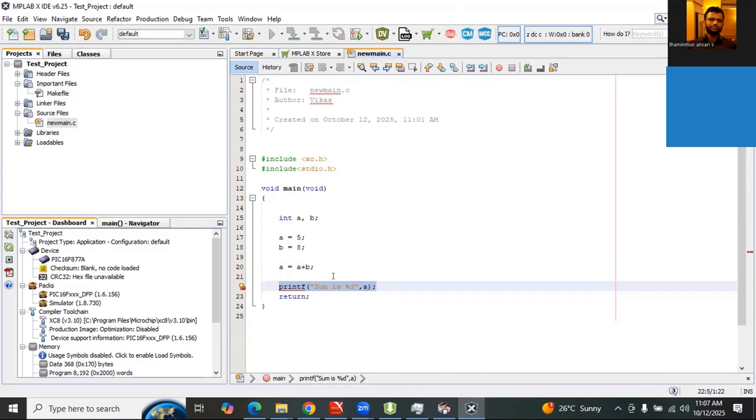Because the computer processes information in binary, the microcontroller will also do the same. When I assign that value to port D, it is a hardware register, which in turn is mapped to pins. Based on the value that I store in that hardware register, the pin state will change. If I connected LEDs to those pins, only those LEDs will glow. So the port thing that I am talking about, right?